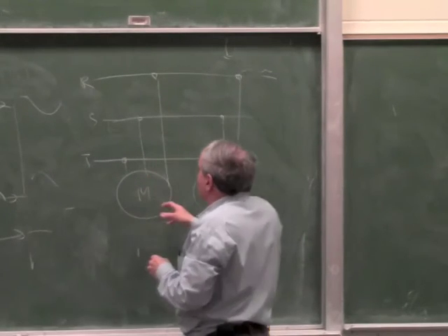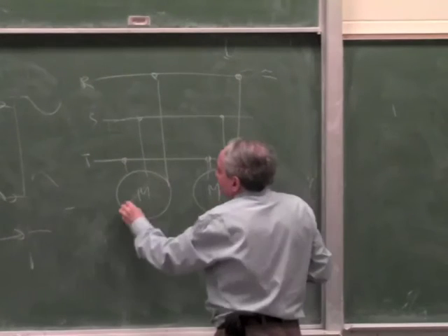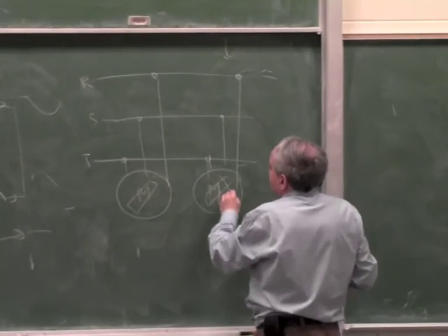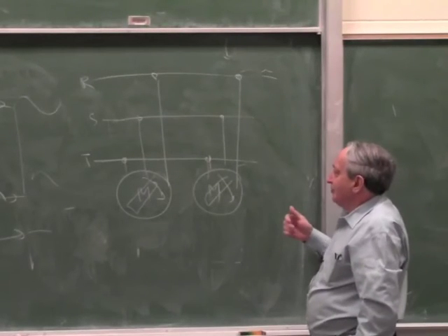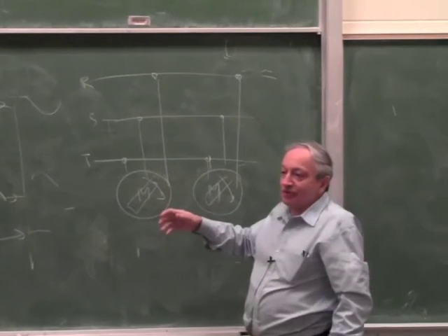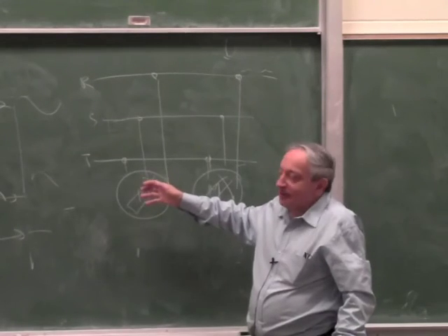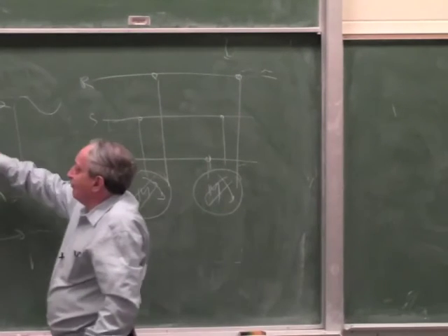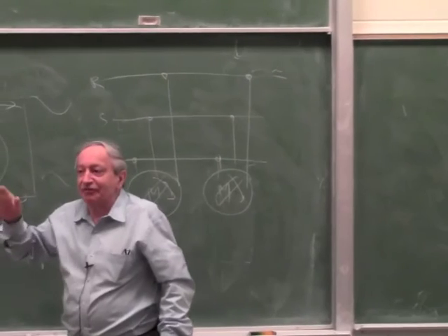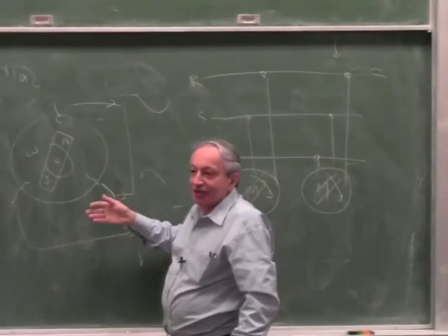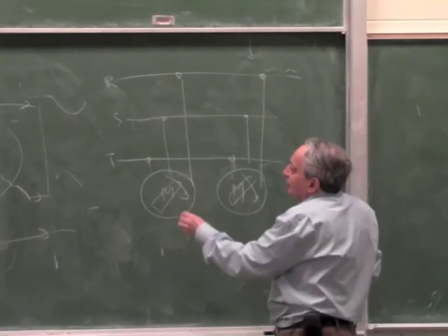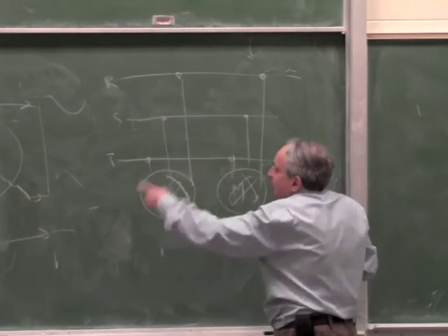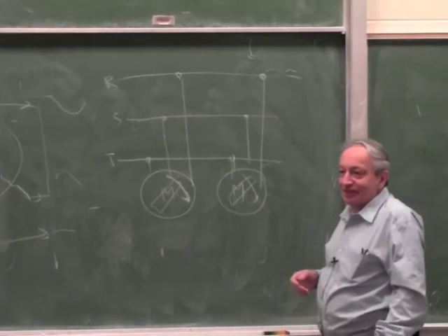If you take one motor and remove the load, it just takes less power, because the magnet will follow and generate an EMF which cancels out the voltage. Now what happens if you not only take off the load, but actually push it to try to make it rotate faster?